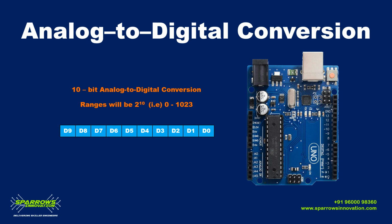For example, if you are using a temperature sensor, the value will be from 0 to 1023, but we need the output value in Celsius or Fahrenheit format. So for that you have to substitute these values in some formulas, so that you can get the temperature value in Celsius or Fahrenheit, right. This is how we can use the analog input values and convert them to corresponding values based on the sensors connected to those pins.